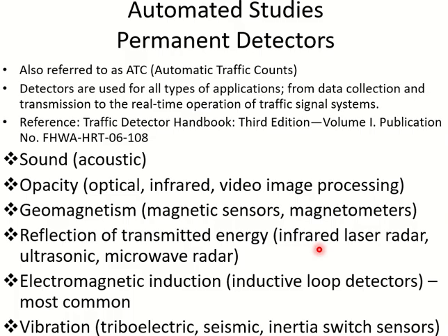And then we have the vibration detectors. They are further under the surface of the road, and when a vehicle passes, it creates a little bit of vibration, like the vibration measured for earthquakes. So these detectors are similar in nature. The vibration is obviously very low. You may feel it on bridges. If you have stood on a bridge when traffic was passing at the side, you can feel it, even on pedestrian bridges. On roads at grade, you cannot feel the vibration, but there is a vibration, and these detectors will catch it and count it.